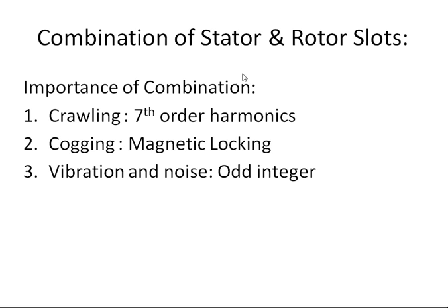The suitable combination of stator and rotor slots requires the following important considerations. We need to consider the effect of crawling, that is seventh order harmonics, also known as harmonic induction torques, cogging, which leads to magnetic locking, also known as harmonic synchronous torque, vibration and noise.